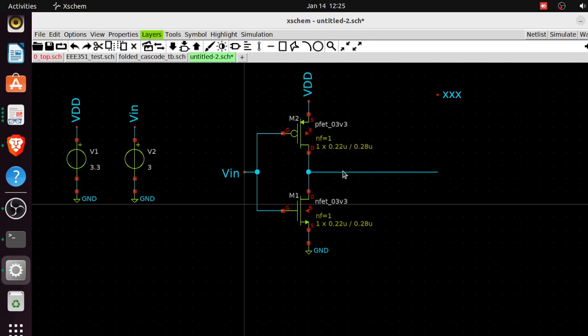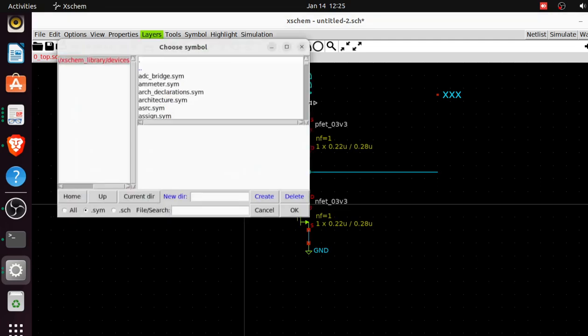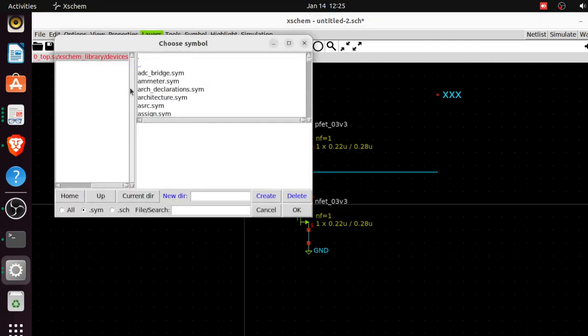So yeah, I go pick capacitor. At this point, you may want to fabricate the capacitor too. If that's the case, you would have to come here to the directory for the PDK. That will be your Skywater PDK. Mine is showing the Global Foundry PDK. I have to come here and search for capacitor. But for this work, there's no intention of fabricating it. It's just there to model.